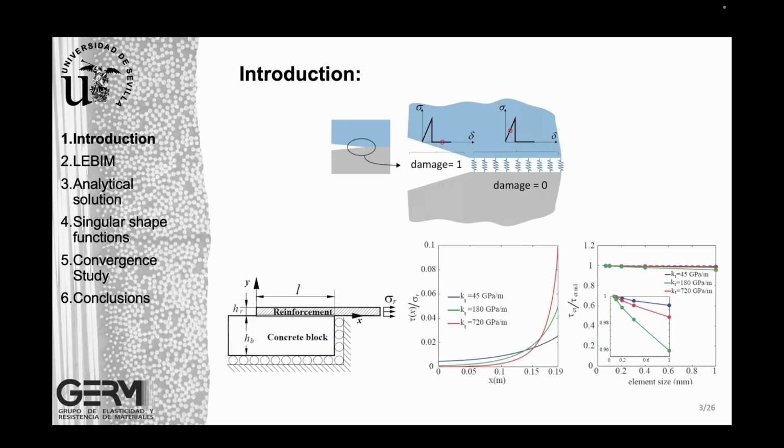One of them is the modeling of the interface with a spring distribution, which is usually called weak interface, sometimes also linear elastic interface, and many other names. But basically, there is a distribution of springs. These springs can have different combinations of behaviors, normal and tangential, but it has a drawback. The main drawback of this model is that when we have stiff interfaces, the singularity that may appear on the crack tip leads to a singularity also in the vicinity of this crack tip.